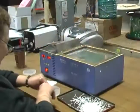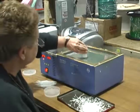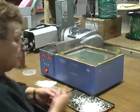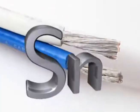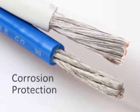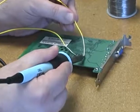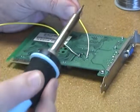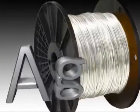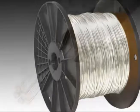In addition to being used bare, copper can also be dipped. Coating the copper with another metal can enhance specific qualities necessary for different applications. For example, in tinned copper, the layer of tin protects the copper from corrosion at high temperatures and makes the wire last longer. Another benefit of tinned copper is that it's easier to solder than bare copper, without a huge increase in cost.